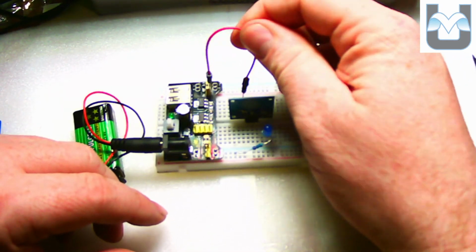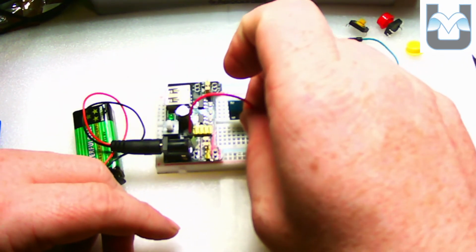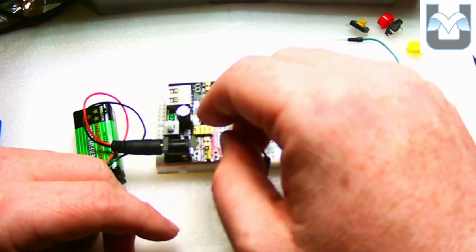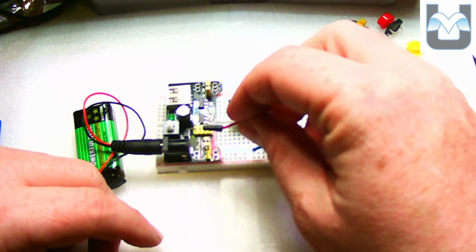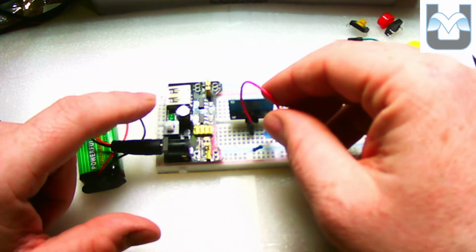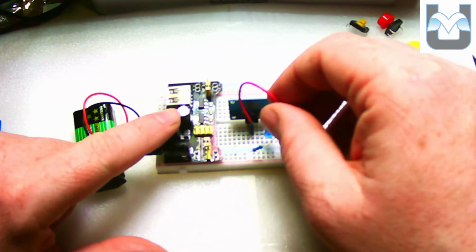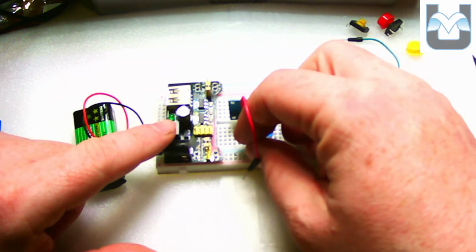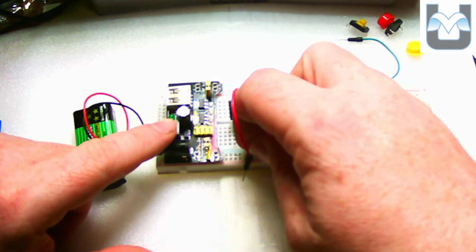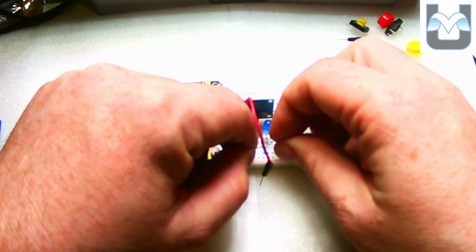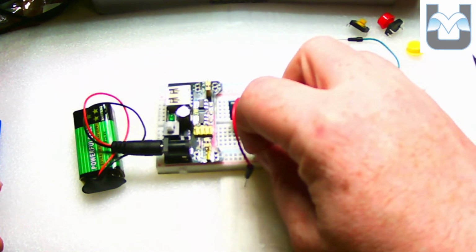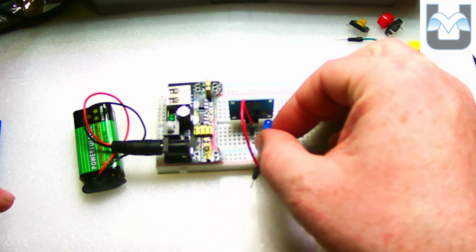Okay. Now I'm going to grab those two wires that I had before, and I know that I've got VCC in the middle. Notice that even though I have some wires dangling here and I happen to be touching stuff on my board, I've turned the power off. This is a good thing to do so that you don't short anything that you're not supposed to short, because that would be bad. It's not a good idea to put electricity where it's not supposed to be on a breadboard, or in any electronics project for that matter.